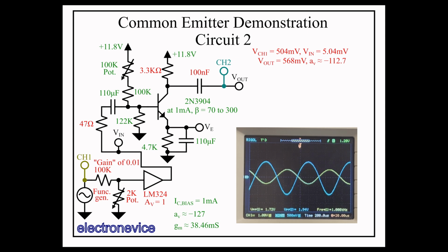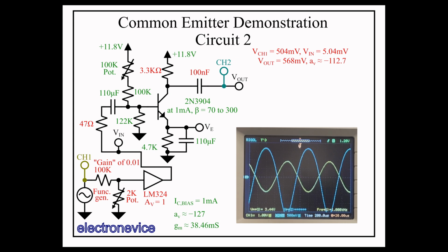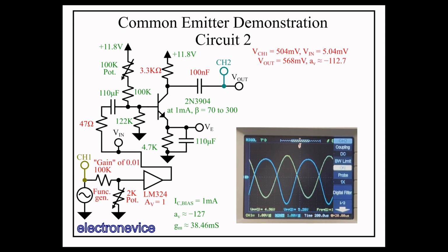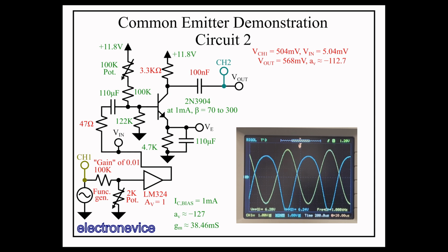And at around 2 volts output voltage, we start to see some nonlinear behavior, which we saw at a much lower output voltage with the previous circuit. So this is again because this nonlinearity is caused by large input voltages, not large output voltages. And so larger gains mean that for a given peak-to-peak output voltage, there's a smaller peak-to-peak input voltage.